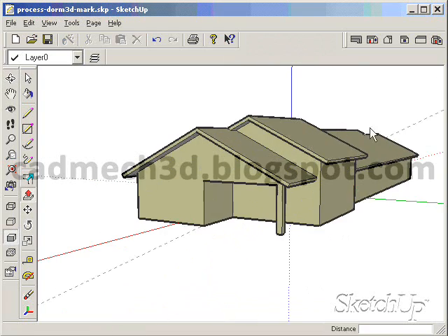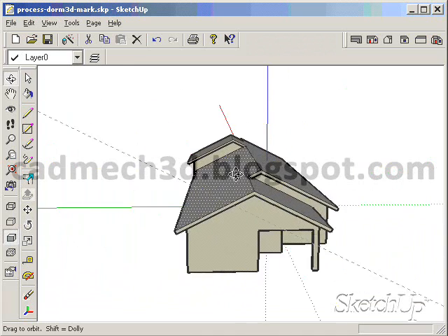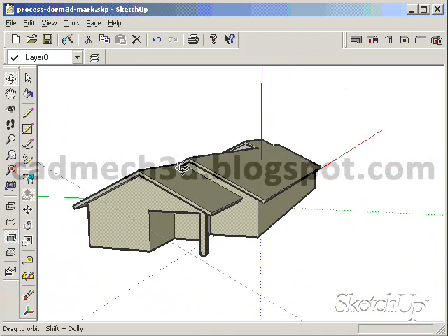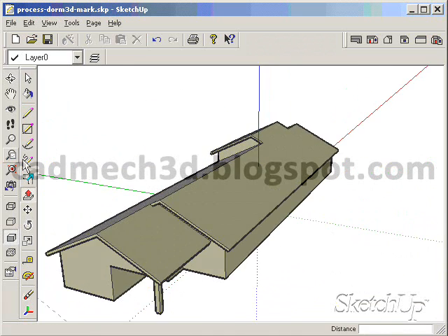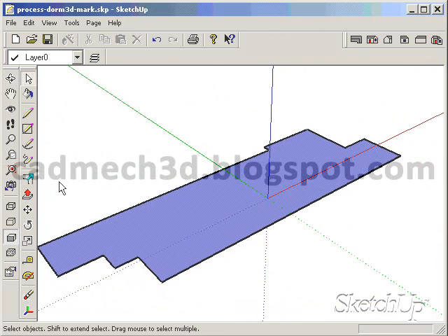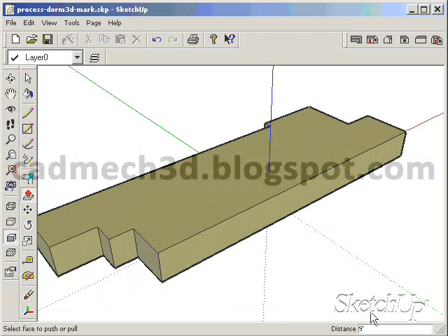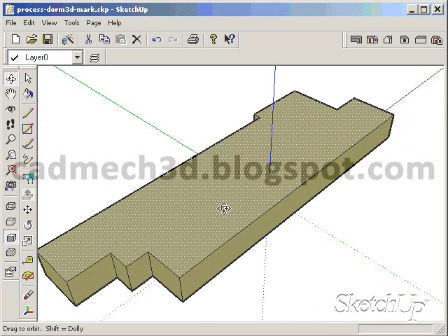Let's look at how to draw a complex roof with extended rafter eaves with sloping undersoffits at the eaves and rakes. We start by using push-pull to extrude the basic building form. Always start by setting the top plate height. In this case, we'll use 9 feet.